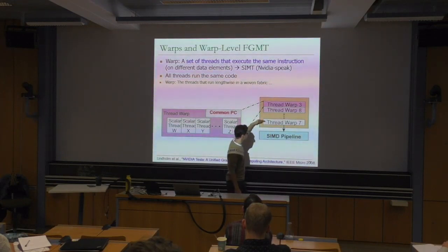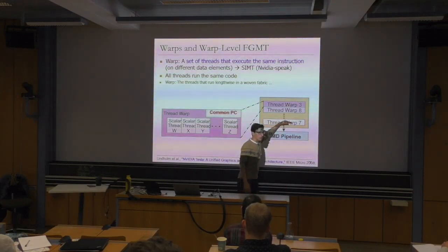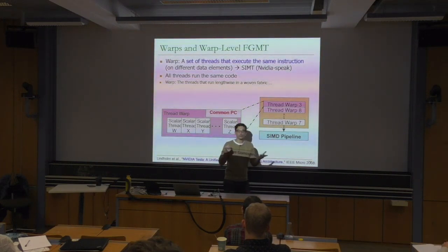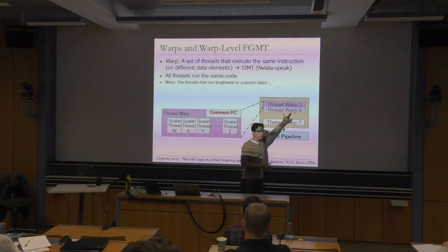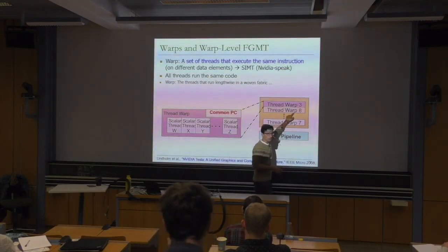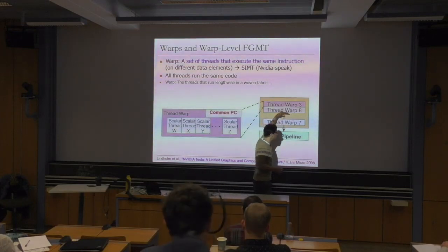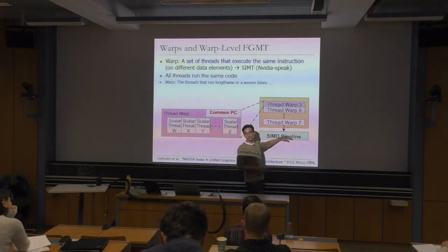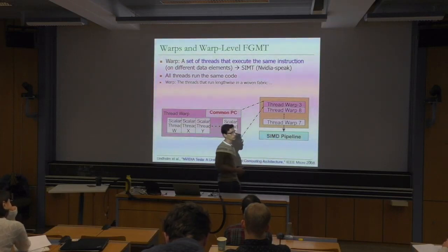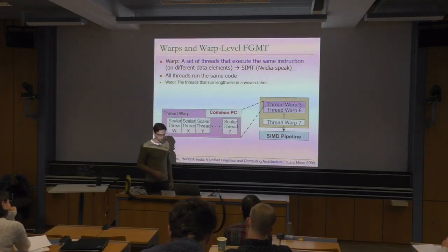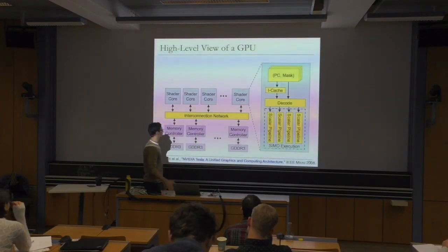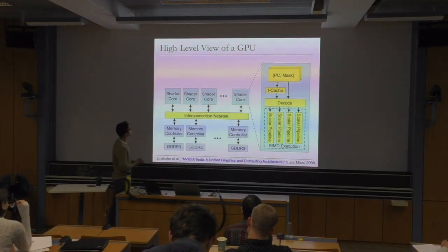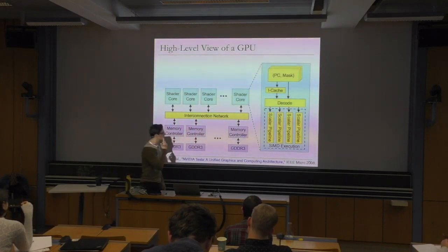For example, here you see the next one is warp 7. Warp 7, but which instruction? For example, instruction 0. So we start the execution of instruction 0 for warp 7. And right after that, we ask, what instructions are ready? It turns out that instruction 1 for warp 8 is ready, because the operands are ready. And if the operands are ready, that can be the next instruction to schedule, the next instruction to issue. Make sense?